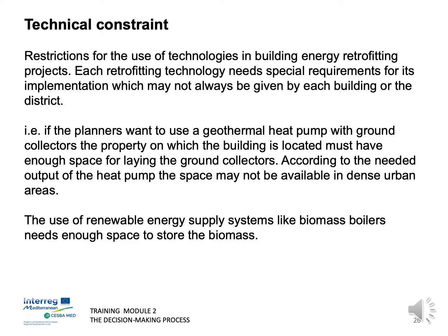Moving on to another constraint, we encounter technical constraints. These are restrictions for the use of technologies in building energy retrofitting projects. Each retrofitting technology needs special requirements for its implementation, which may not always be given by each building or district. What do we mean here? So, if planners want to use a geothermal heat pump with ground collectors, the property on which the building is located must have enough space for laying the ground collectors.